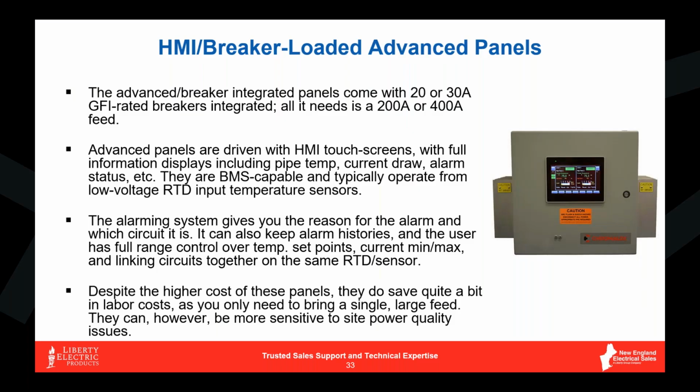The nice thing about these particular panels, again, is that they will tell you if you have a fault, what it is, what circuit it is. So it takes a lot of guesswork out of it when you have issues. The only real disadvantage to a lot of these types of systems that utilize quite a bit of microprocessor strength is that they can be vulnerable to power quality issues. That's generally the big issue that we run into with them.